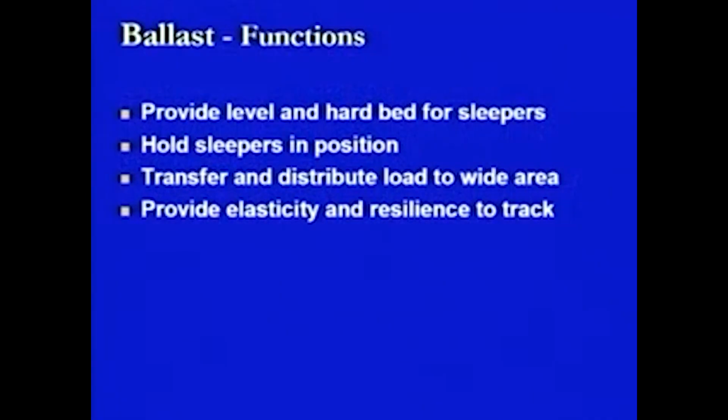It should be able to provide elasticity and it provides the resilience to the track, that is another aspect. What happens in this case is, because of the type of the material which is being used and the voids being placed between those materials, there is a sort of a mutual arrangement of the particles with respect to load, and in this form whatever the loads are coming from the top, as soon as the load is being removed, because of the elasticity the track comes back towards the normal condition, and that is how it maintains its levels, and that is what the resilience of the track is.